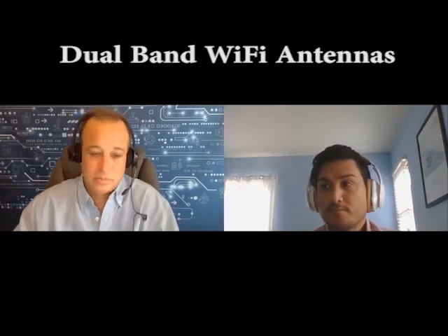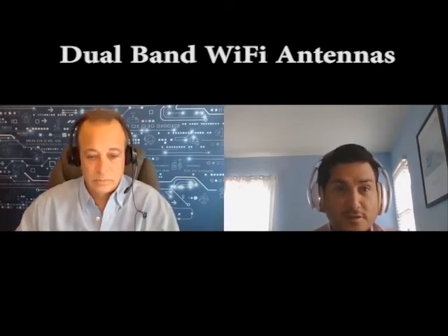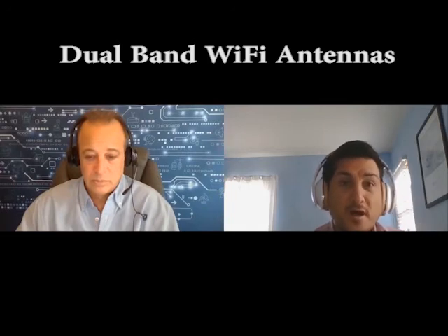We have a dual band antenna that is only 1.6 by 0.8 millimeters with a 5 by 8 millimeter effective area that is used in Wi-Fi modules, or in the case of a Ring doorbell camera that uses Wi-Fi, that has a really, really small usage area on the PCB and is very effective. We're currently developing a tri-band Wi-Fi antenna, because as many of you know, there's a Wi-Fi 6 protocol that is becoming more and more popular. So we'll have a 2.4, 5 gig, and 6 gigahertz antenna coming up in the fourth quarter.